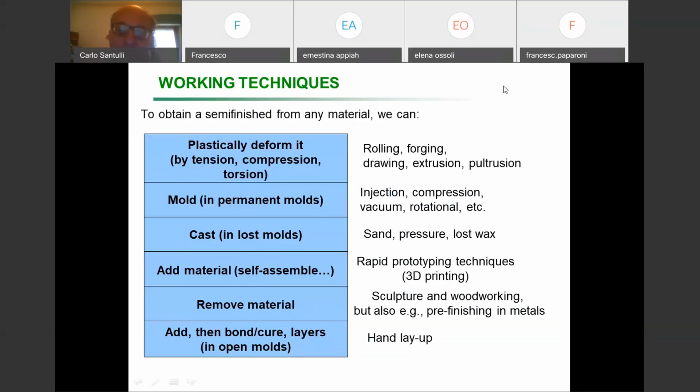We assume there is a mold, like it is the case in concrete. There is a kind of mold where you pour down concrete, but well, it's something which is not very expensive, and also the precision of that mold doesn't really matter. In the case of plastic, the precision needs to be absolute because the mold costs many, many times more, in some cases millions of times more than the piece we are going to produce.